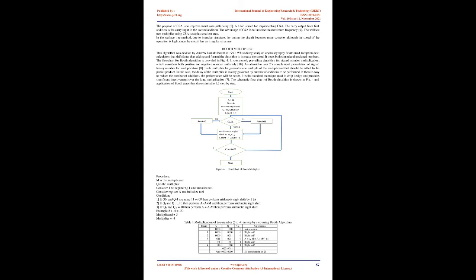Array multiplier consumes more power and an optimum number of components is required. It requires a larger number of gates, and therefore the area also increases. So, the array multiplier performs poorly in terms of area. It is a fast multiplier but hardware complexity increases due to the large number of gates. The schematic representation of the conventional array multiplier with CSA is shown in Figure 1.